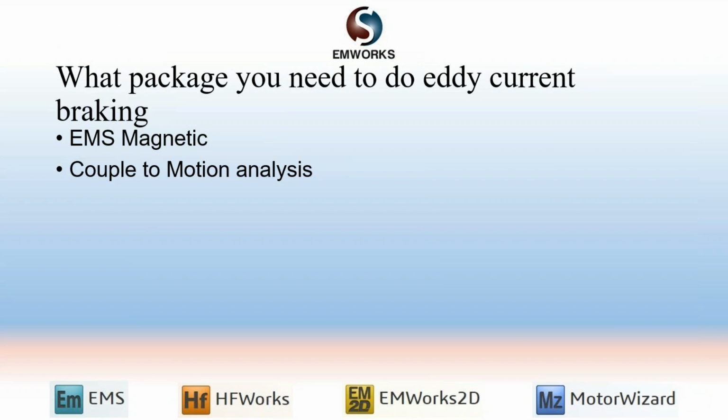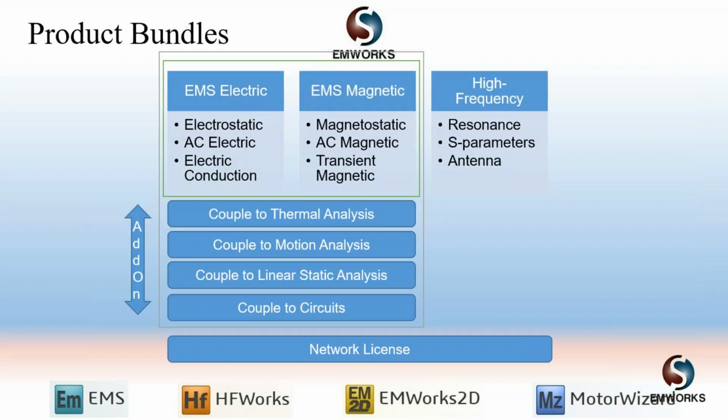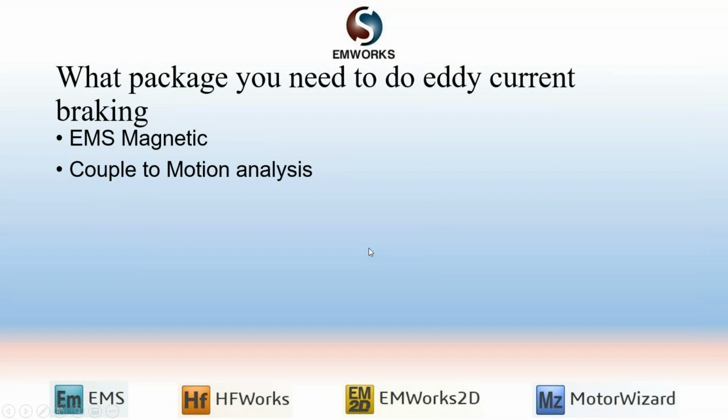Now, to do eddy current simulation, what kind of package do you need? If you remember, we use transient magnetic and we coupled to motion analysis. So what we need is EMS magnetic and coupling to motion. That's the bundle that you would need to do eddy current braking systems and similar types of applications.